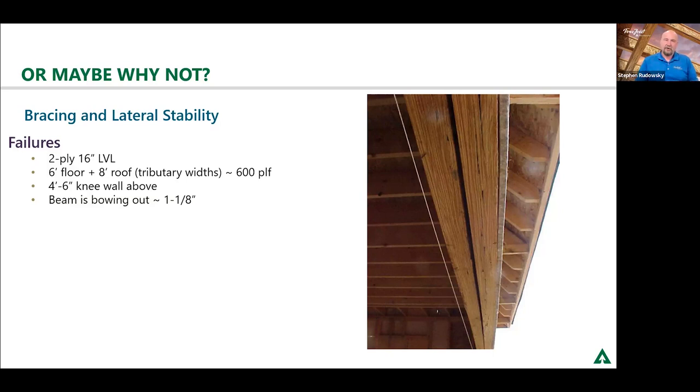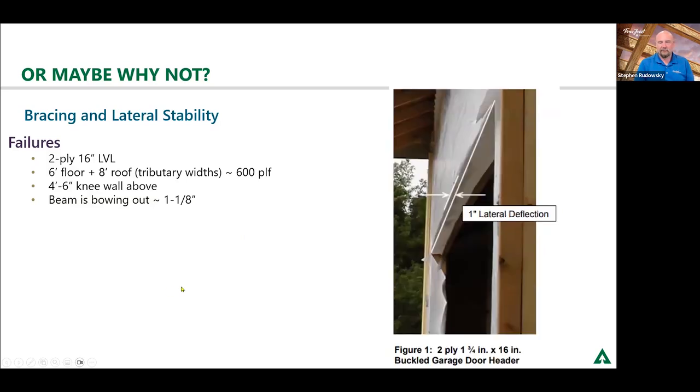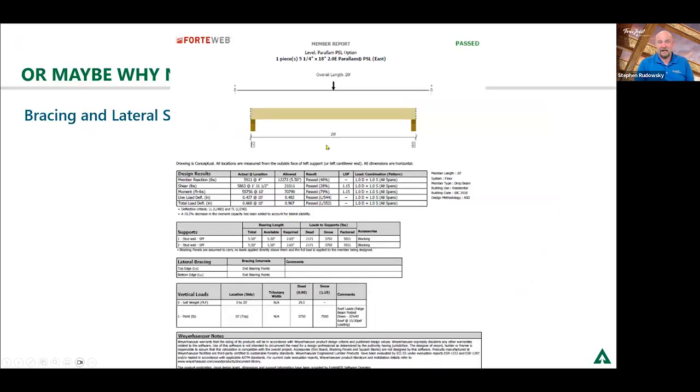That's something that we would have to go through a third-party engineer for. We don't look at how the actual bracing is being applied. We can only tell you that bracing is necessary. We can tell you that floor joist bracing is 100% needed. And if you want to learn a little bit more about it, TJ9000, if you go to the Weyerhaeuser website, wy.com, look at TJ9000, page 25 is going to have a little bit more explanation on suitable ways to prevent this from happening, outside of really going with, like I said, that solid section member.